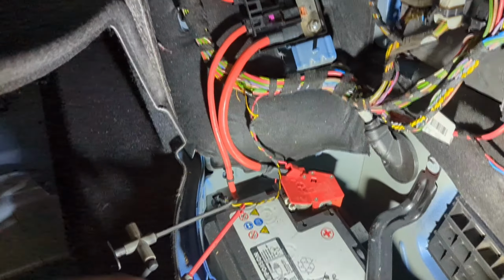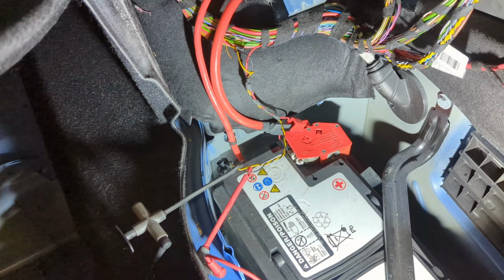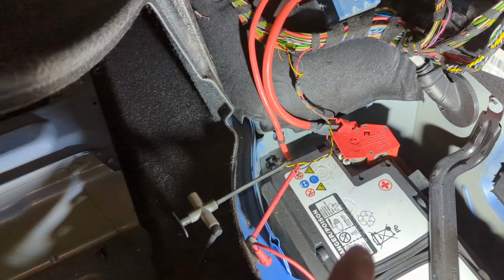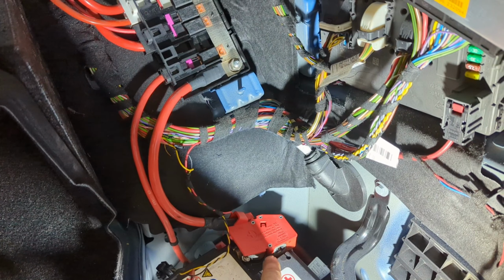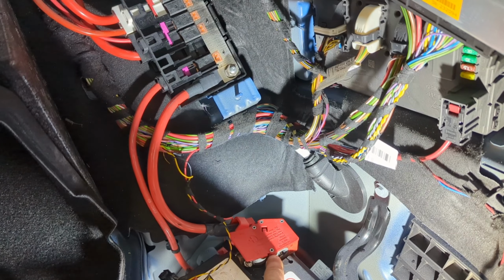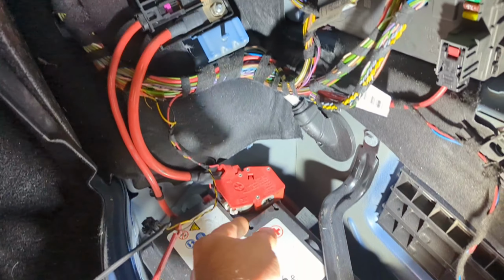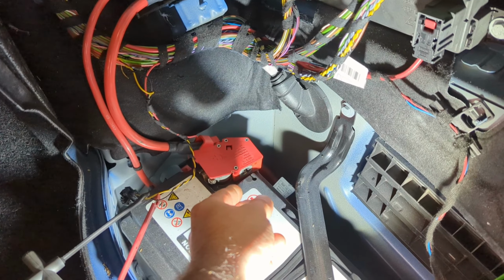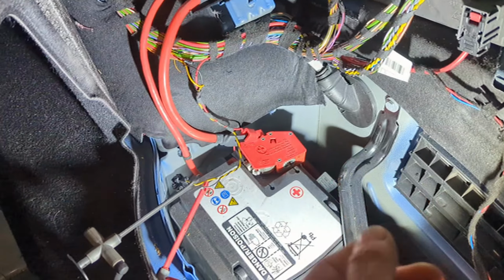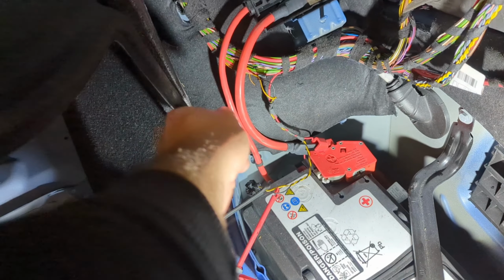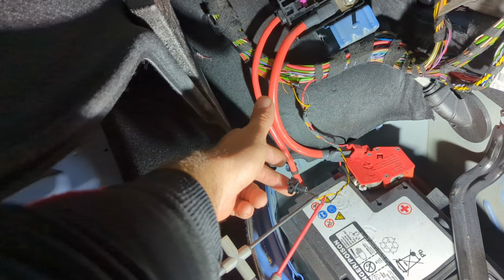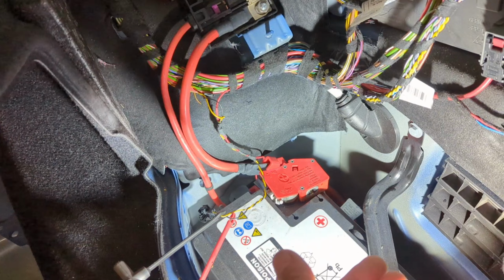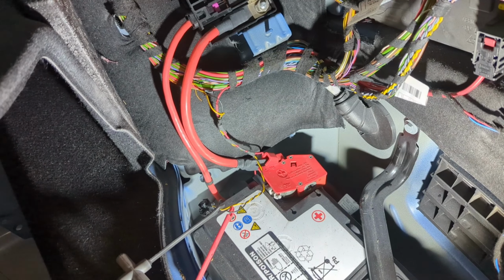So basically what's happening is that when these BMW vehicles are in an accident, there's a little terminal on here called your battery safety terminal. Inside of here, when you get into an accident, it creates an open circuit in the system due to the igniter igniting the gas charge in the B.S.T. terminal. This is basically just an airbag connector, and inside of here we have a 2 ohm resistor, just like any other type of airbag system.